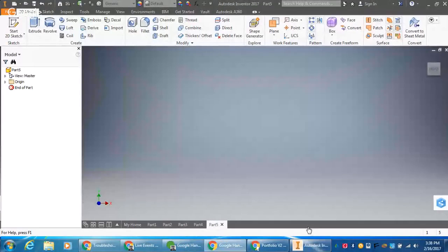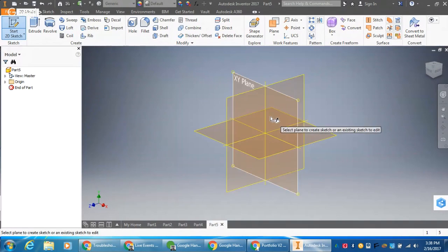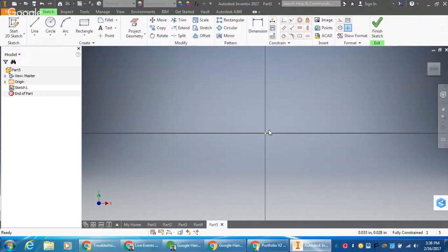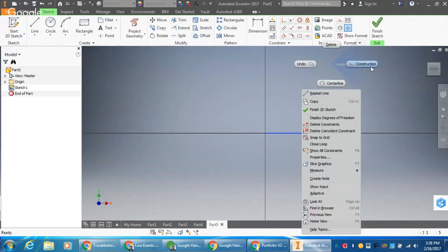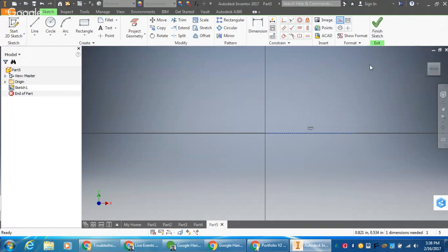Alrighty, so here we go. How do we start this? Now, obviously, we're going to have to revolve this. So what we need is a central axis. I'm actually going to be using this x-axis as our central axis. So it's easier just for me to click and draw a quick little line, hit escape. Then I can right click on that line and make it a construction line. What that does is just gives us something to revolve around.